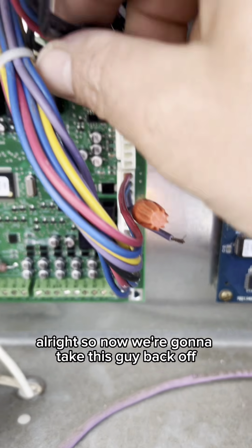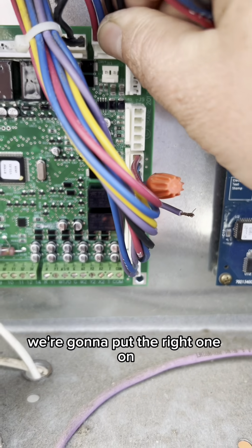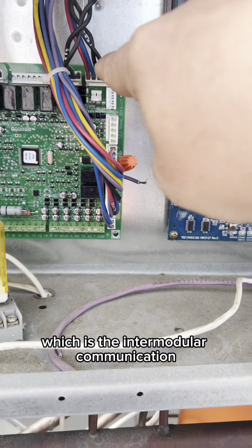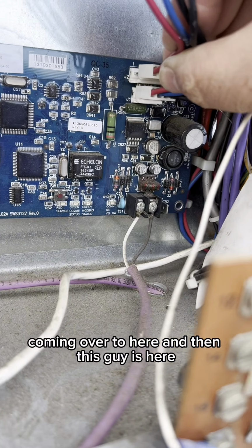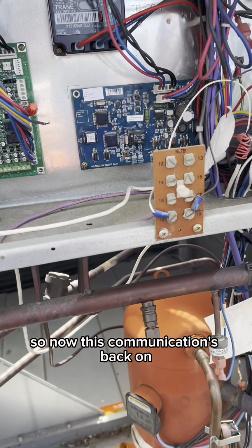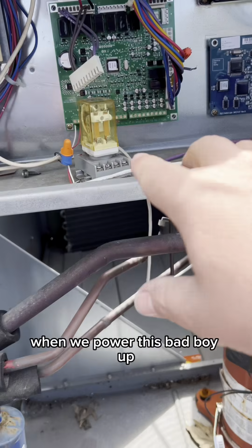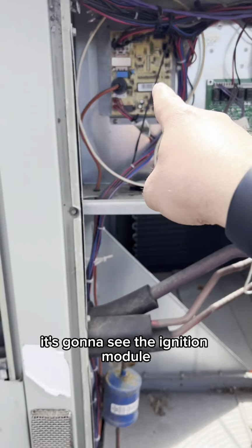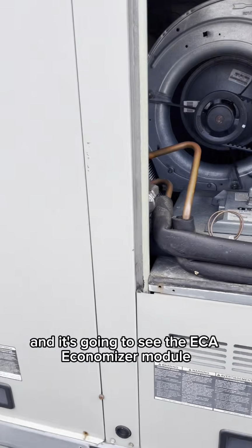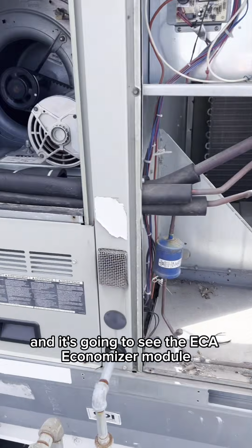All right, so now we're going to take this guy back off. We're going to put the right one on, which is the intermodule communication coming over to here, and then this guy is here. So now this communication's back on, and everything should be good. When we power this bad boy up, it's now going to do a who-is. It's going to see what's connected. It's going to see the LCI, the ignition module, the RTOM, and the ECA economizer module.